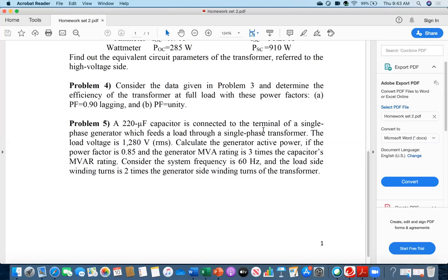Remember that in class I was discussing the necessity of connecting a capacitor at the terminal of an induction generator. So therefore, it should be in parallel, not in series. I thought it was series because it said terminal instead of terminals. From the statement, it did not explicitly say series or parallel, but it will be in parallel.